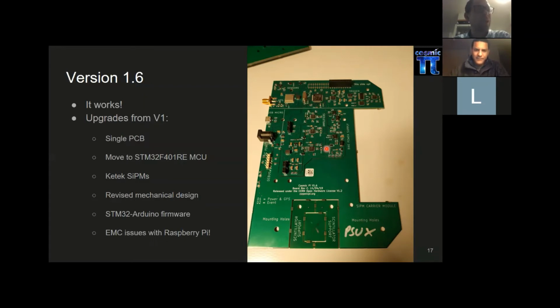And fundamentally here, we changed our mechanical design. So you can see the board has this kind of C shape with a cutout missing. The cutout is actually a riser, which has the SiPMs on it and can be plugged back into the board when you've snapped it off into these 4 connectors here. And the scintillators run in this direction. We'll show you some pictures of the inside.